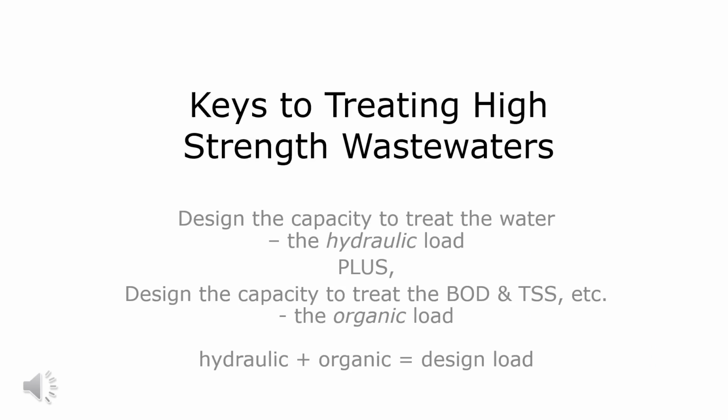The key to treating high-strength wastewater is to first design the capacity to treat the water itself, the hydraulic load, but also a second part is you have to design for the organic load, the BOD, the TSS, etc. So you are very used to using the first half of this, but now I'm going to ask you to add this second part. It will take some math on your part, and you may not be used to doing this, but I'm sure you can do it.